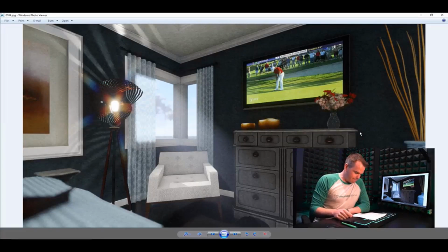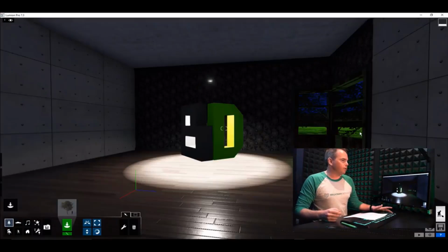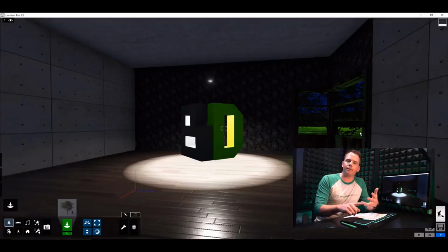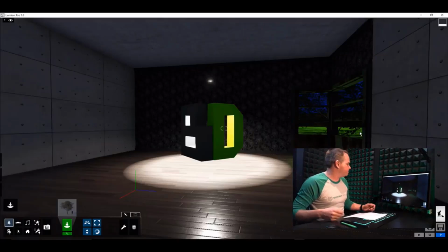So in order to do that, when I was kicking things off to write this blog post, I realized that I really needed to study the Lumion light sources. So basically there's 5 or 6 different light sources that we're going to talk about. You've got the sun and spotlights, omni-lights, light fills, emissive materials, and line and area lights. So all these different light sources behave in different ways. And so it's really important that we isolate that light source so we can understand what it's doing.